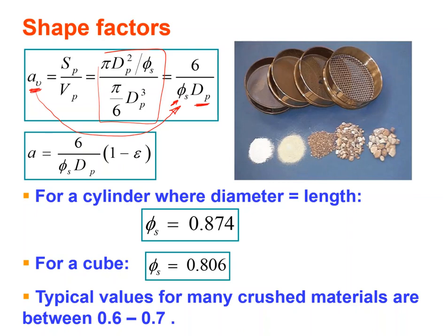This dp is not the old one, which is the diameter that we defined before. Now this is called nominal or equivalent. How do we get it? We get it from sieve analysis. We put the particles inside this sieve, نفس المشخالة, and then I know the particle, or let us say the hole size, and this is called the equivalent or nominal size to be substituted here. And then in order to correct for the diameter, I will use the shape factor.